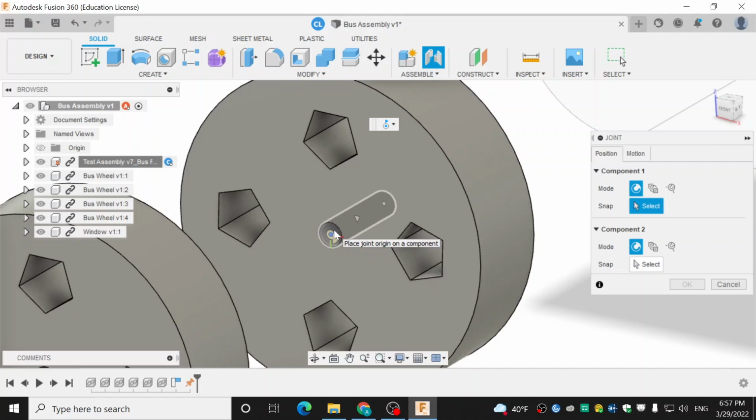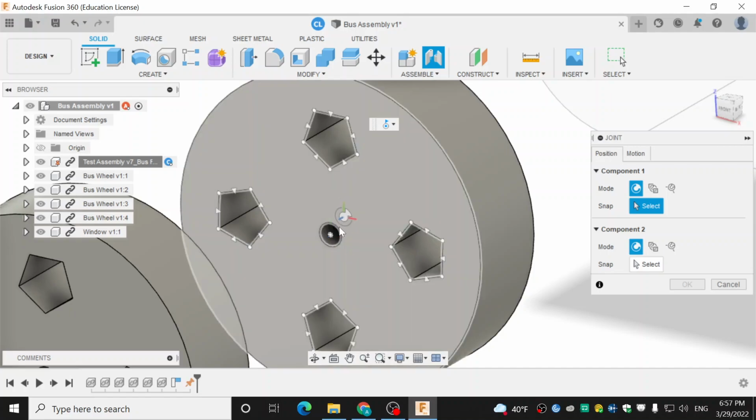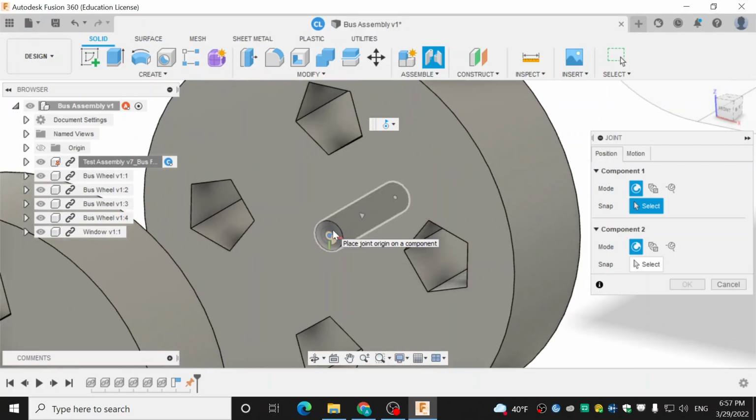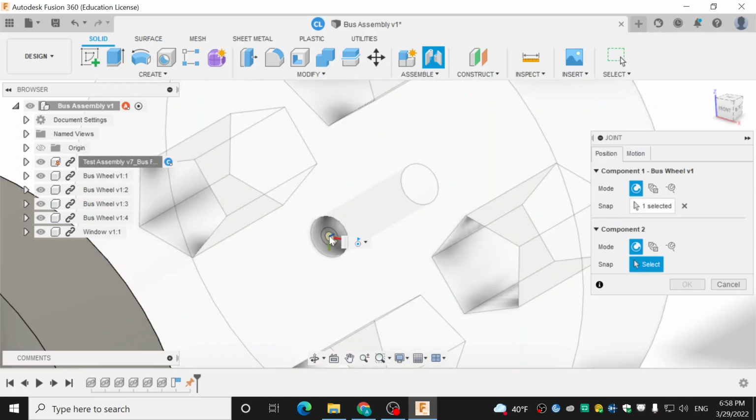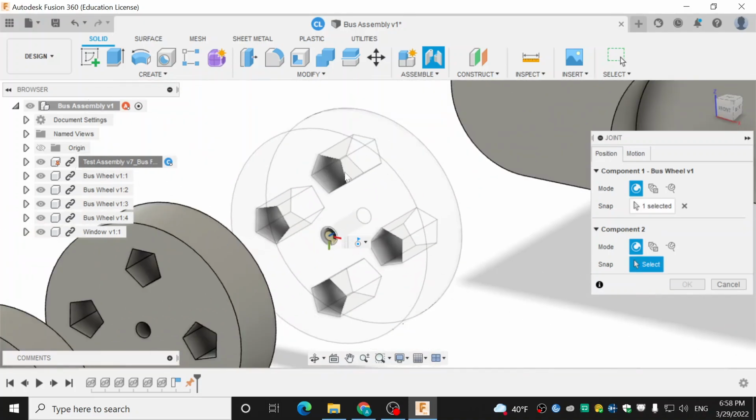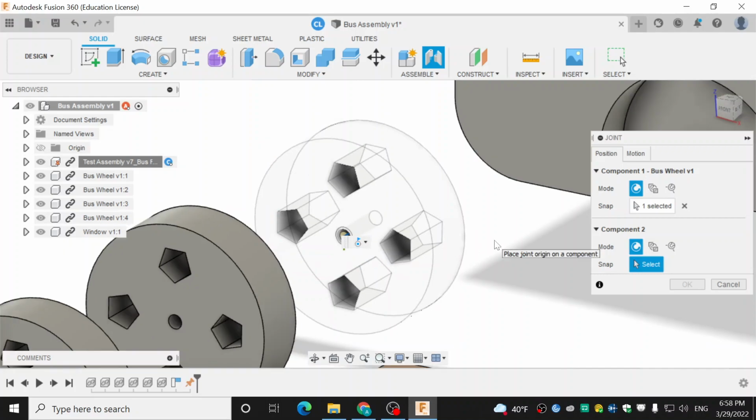They require 2 different types of connections, a point and a plane or an axis. So we're going to hover over it so that we see the axis as well as our little tiny coordinate plane system right here. It's red, green, and blue. We're going to click on that. Now that that's transparent, it means that's one of our components that we're connecting.